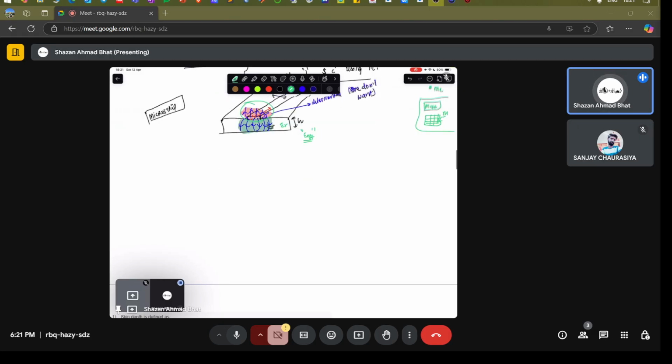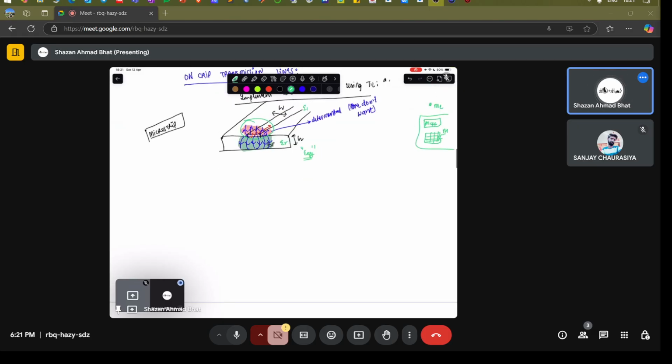We define something called effective permittivity, and if you see what happens when we draw the effective permittivity versus the dimensions, the dimensions being the ratio of W over H, which is very essential when you fabricate these microstrip transmission lines.